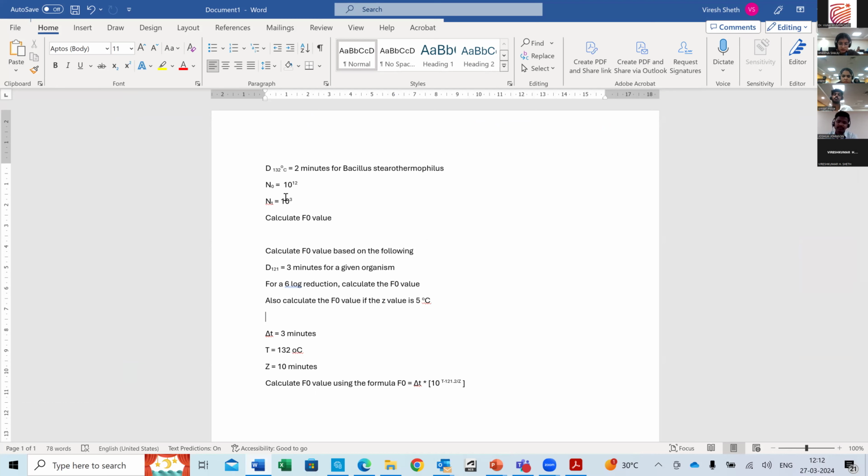This is the theoretical value. Now, when I did the F0 calculation on the autoclave and took the temperature every 5 minutes, knowing that my Z value was a fixed value of, let's say, 10, if my F0 value fell below 24 minutes, it would mean I have a problem inside the autoclave. Understood? Yes, sir.